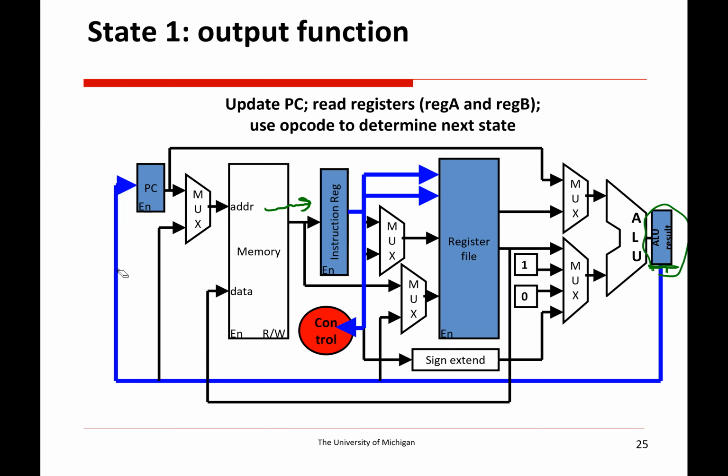Norman asked, in the fetch cycle, the instruction opcode is fetched? Yes. And the PC is incremented? Not quite. We have an incremented value of the PC, and that's getting stored in the ALU result. It's not until the decode stage that we're actually taking that value and writing it into the PC, effectively incrementing it by 1. Again, there's no inherent reason that we couldn't have done that on the last cycle, but maybe when we tried to design that, the clock period was too long to do both of those operations in one. So we're just splitting it up into two operations here.